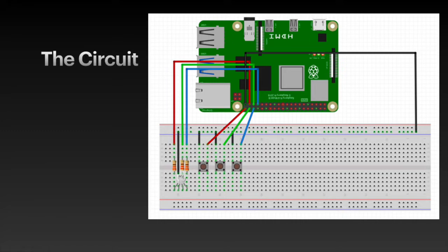Now in this program, how it will work is the LED will start off for all 3 colors. Then as you push a button for one of the colors, it will increase the brightness of that color a certain amount. Press it again, it'll increase it more. And with each subsequent press, you'll increase the brightness until it reaches a duty cycle of 100%. At that point, if you press that same button again, it will make that color go to 0% duty cycle or off. So it kind of is a circular control system for the red, green, and blue in the LED.